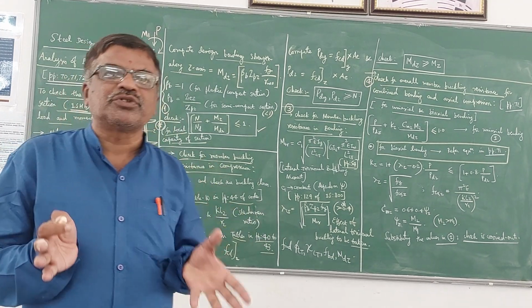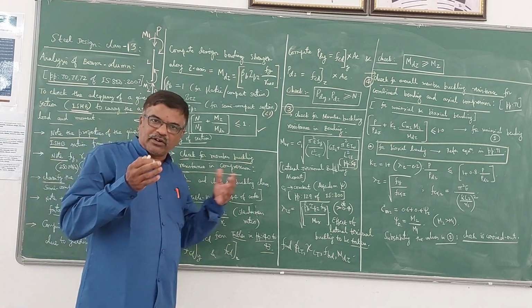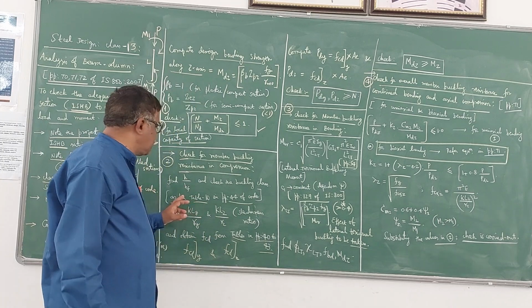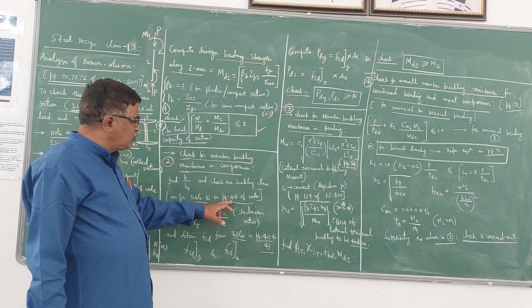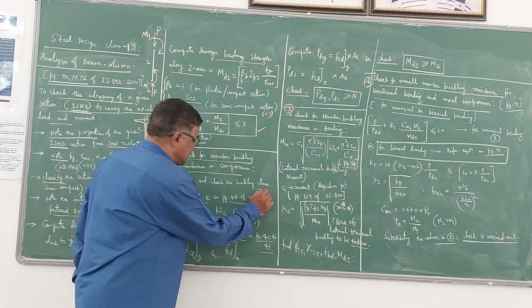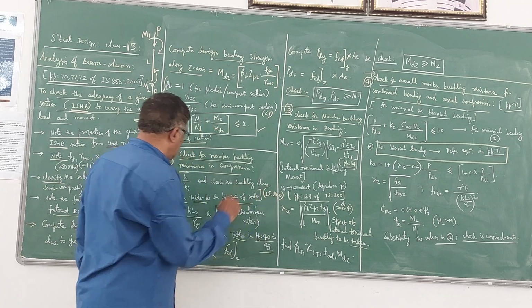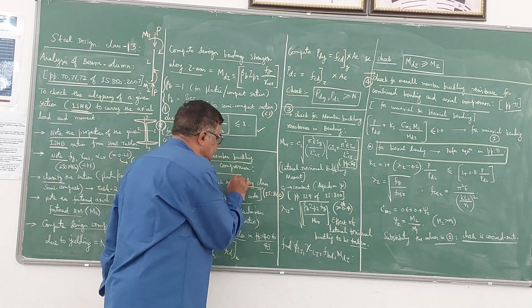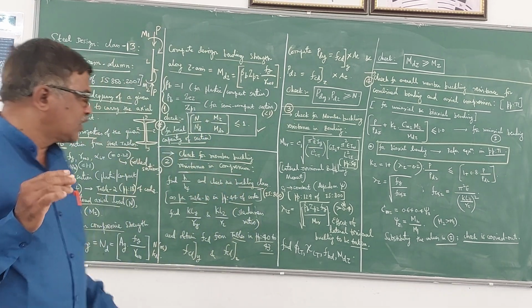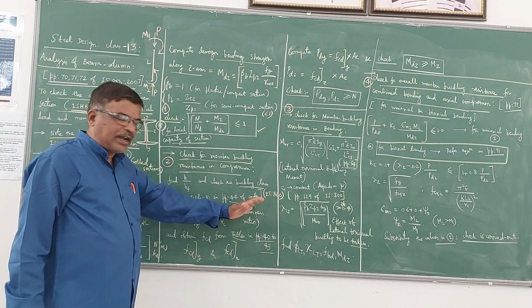This you have used in the design of compression members in steel design in your undergraduate BE course. So we have to use the values provided in Table 10 on page 44 of IS 800. From that you can get the buckling class. There are 4 buckling classes, A, B, C and D. So in which class that member comes, that we can decide.